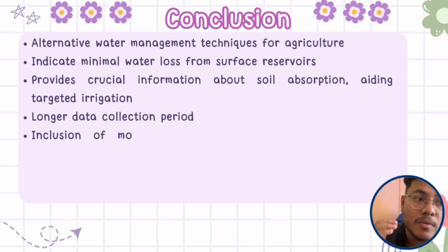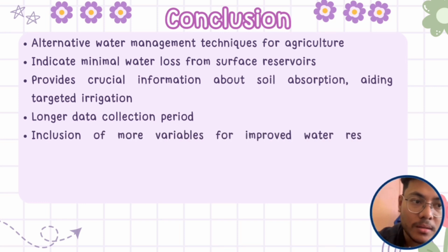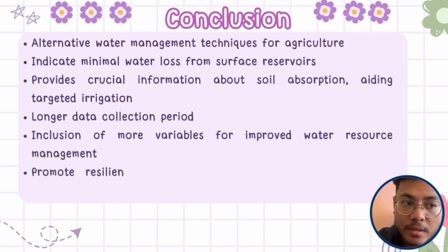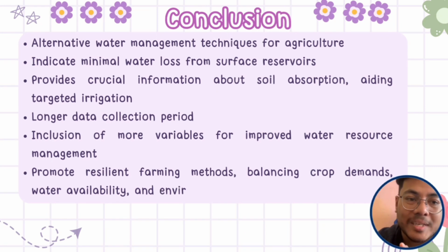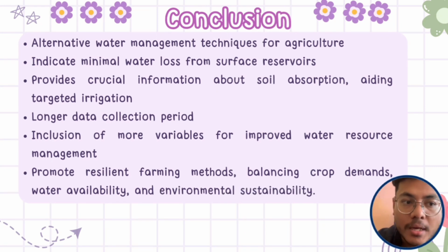The high evaporation rate, exacerbated by tropical heat and moderate winds, further reduces water availability by restricting runoff and infiltration. The infiltration test at 4 locations showed decreasing rates over time, indicating soil saturation and characteristic of loamy or clay soil. So that's all from me. Thank you.